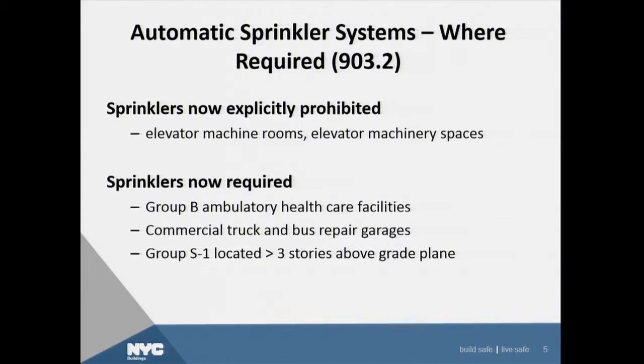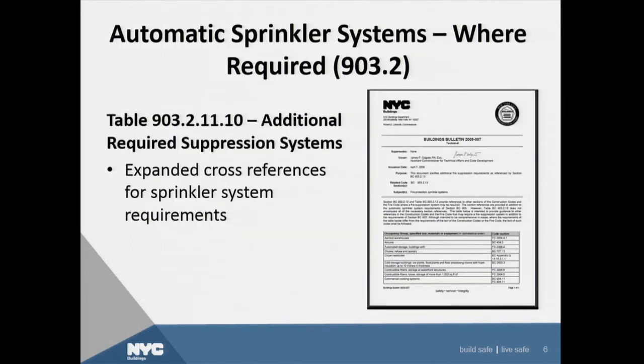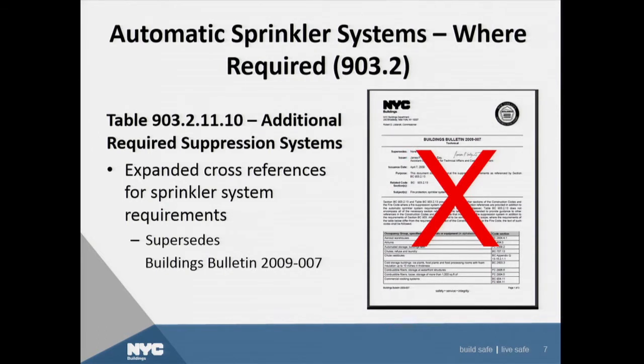There are some new requirements for commercial truck and bus repair garages, and certain S1. S1 is storage, and S1 is the combustible storage, the storage that's much more flammable, and there's a new sprinkler requirement for that, so you can be on the lookout for those. Now, some of you may remember this bulletin that we issued to give cross-references to other parts of the code that have sprinkler requirements because they weren't all classified. We're getting rid of that.